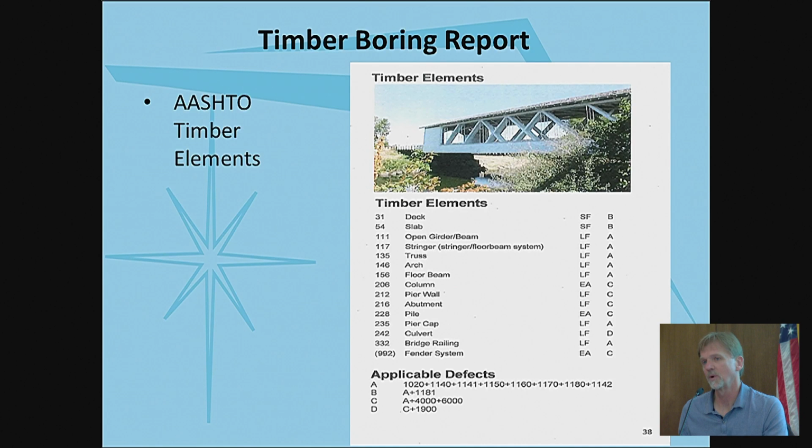As we mentioned before for the fracture critical inspection and the underwater inspection, when you do your timber boring, you can indicate on your report the condition state of that member, but that will all be summarized in your routine bridge inspection report. There are many different timber elements, as you can see here, and I know many of you have slab decks, timber piles, timber caps, and timber rail. Many timber elements need to be checked and shown on a timber boring report.